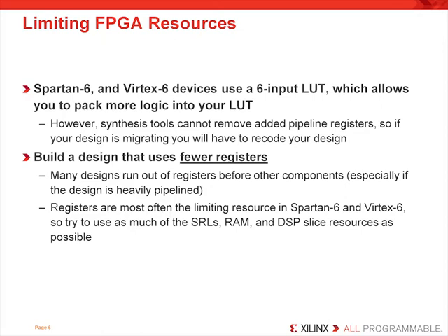For example, designers often don't use the shift register LUT in their design. Recall that this resource saves registers from being wasted to balance a pipelined application. Remember that it is important to use the appropriate resource and check that it was inferred properly by your synthesis tool. There are also other reasons inherent in the registers available in the FPGAs that may prevent users from inferring the best resource, specifically the shift register LUT, the block RAM, and the DSP slice resources.